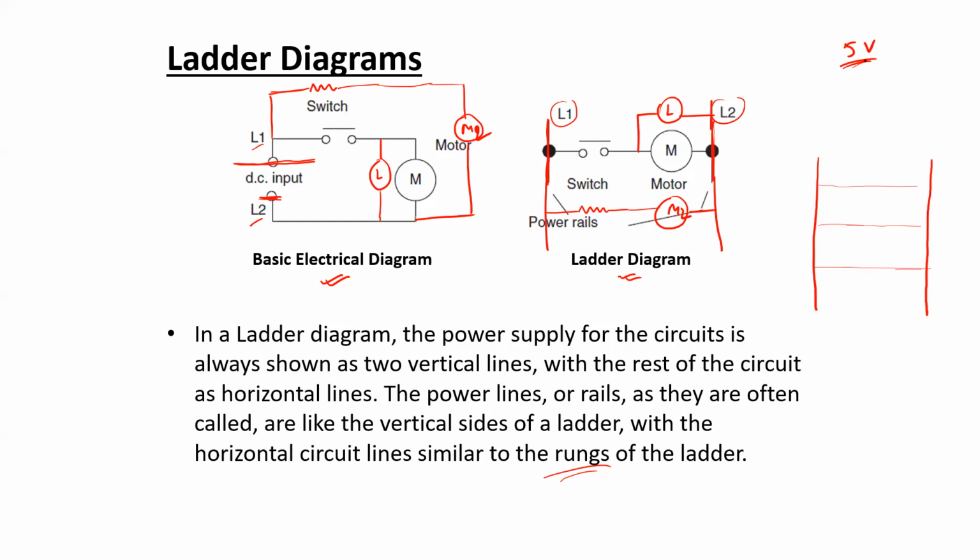And if you ask in general about a case with different voltage sources, then a single ladder diagram would not be sufficient to represent that electrical circuit in ladder diagram form, because a single common voltage source is necessary in order to draw the two vertical lines and all the elements that are shared by that particular source.